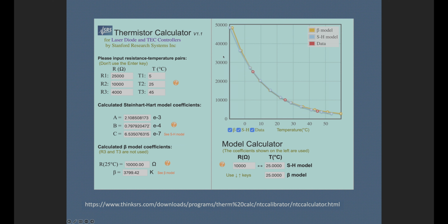Now we're at the top end, 120, 122 C. We're looking at the Honda coolant temperature sensor. We're going to continue to take readings as it stabilizes out and goes down.